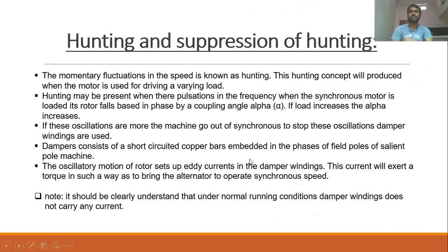So next, hunting and suppression of hunting. We have discussed this so many times in detail. Hunting is nothing but momentary fluctuations that occur when some external disturbance affects the machine. At that time, the rotor falls back with respect to the stator flux, and it tries to follow the stator flux here. We even considered the same example while discussing synchronous generators. I hope there is no need to discuss in depth.